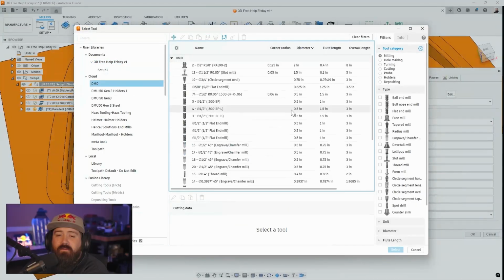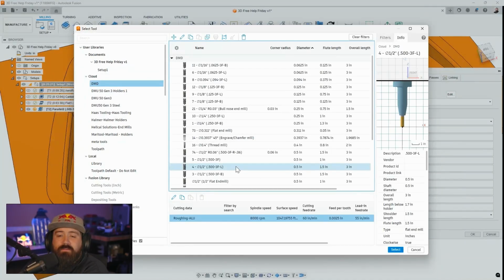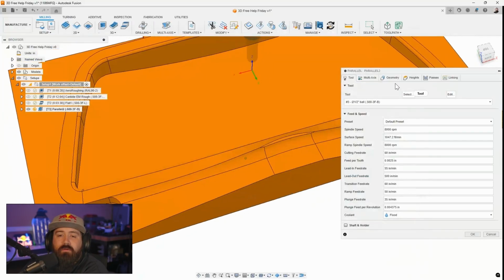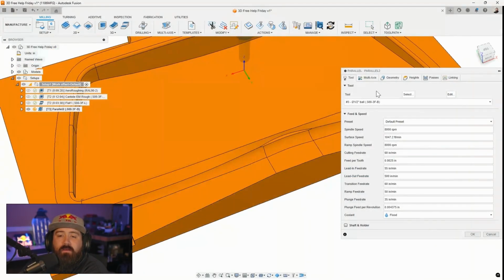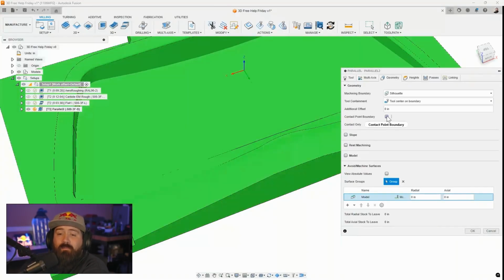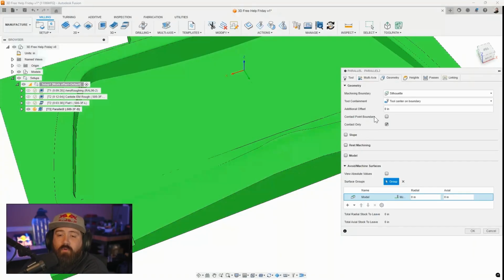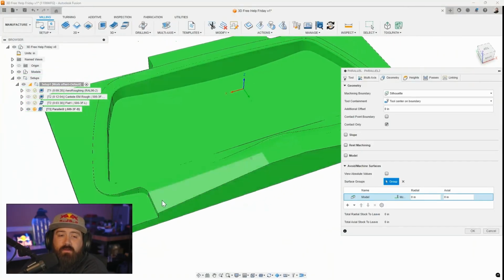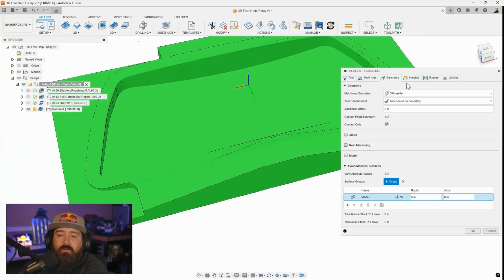Oh, I think you get morph there, Jonathan. Morph is another one I would try. Morph would work for this because it's relatively low slope. Morph doesn't work very well when you need steeper. It's when you need contact point boundary, because contact point boundary doesn't get added past morph. But I think we find a spot for that. We could probably show on the end here where morph wouldn't be great.